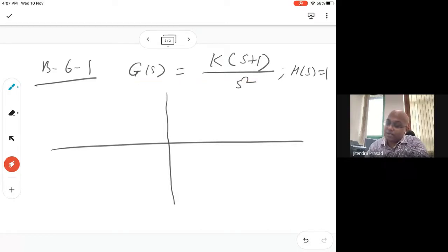In the root locus method, given the open loop transfer function, you will know beforehand all the possible points where the roots of the closed loop system will be, so that you can decide accordingly and in the real system choose one of those points. There will be a plot showing where the roots are depending on the value of k. As you change the value of k, your points also change, and all those points together are known as the root locus.